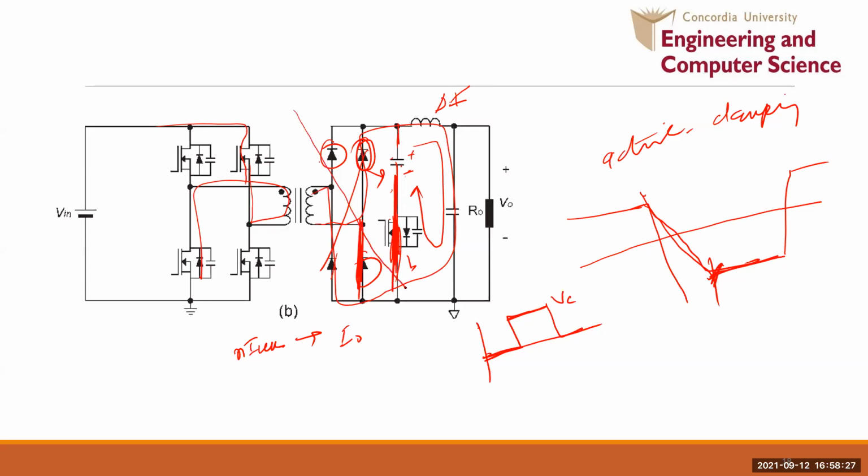So when the power is taken from this diode pair to this diode pair, or from positive to negative, during that time the clamping switch is on, this difference flows through this, and this is short circuit. Voltage across the diode is basically capacitor voltage, and that's it. Clamping happens by this. So you don't need 4 RC or RCD snubbers at all, which is causing losses. Only the loss in one switch, as well as the difference flows through the two diodes. So two diode losses versus one switch loss, even the difference. So this is better still. So this was found to be an efficient solution.